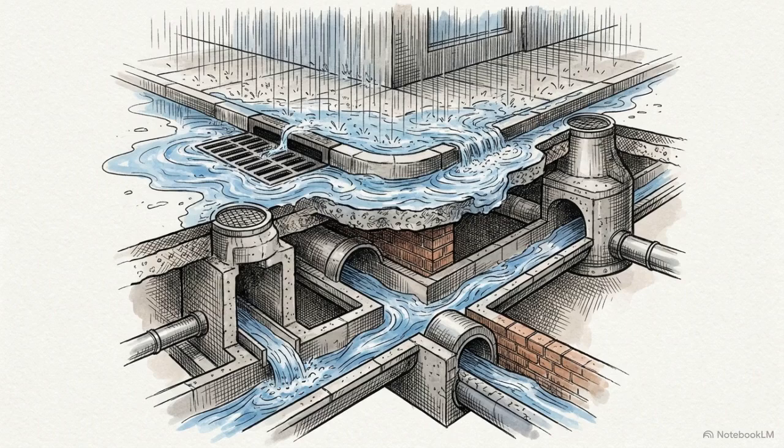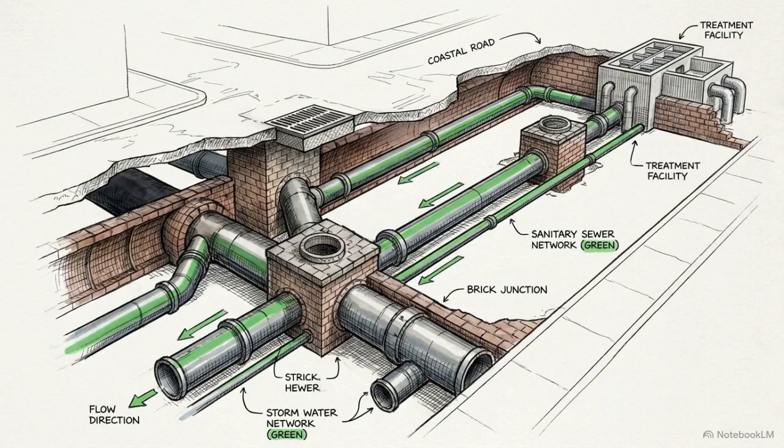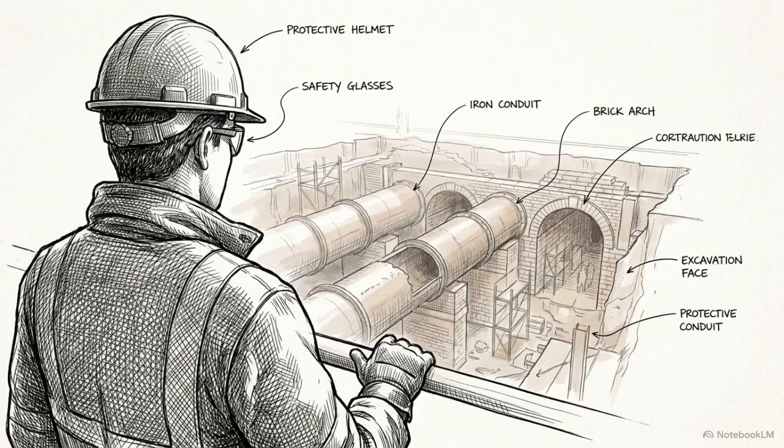Finally, question 15 applies this logic to a coastal township with high rainfall. Since high rain increases overflow risk, we avoid combined systems. A new township allows for the planning of a separate system, making option B the best engineering recommendation. Navigating negative framing and scenario-based questions is the transition from memorizing facts to applying engineering judgment.